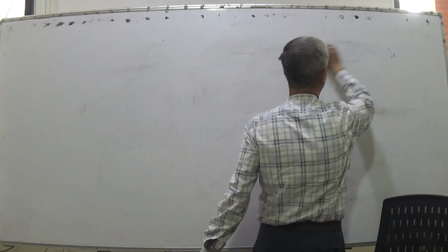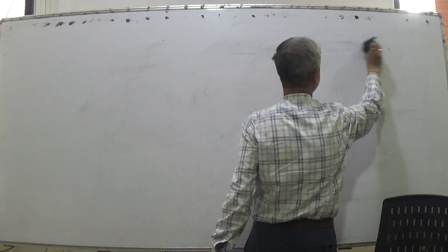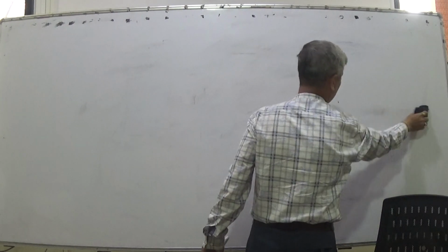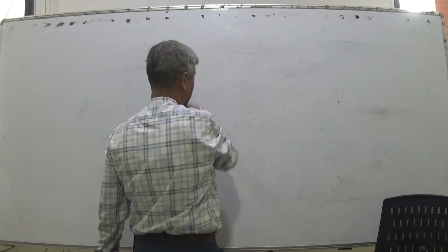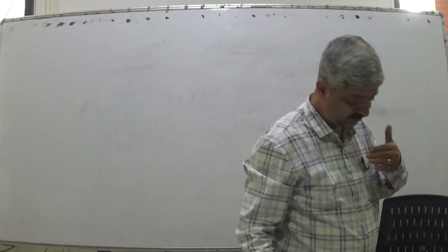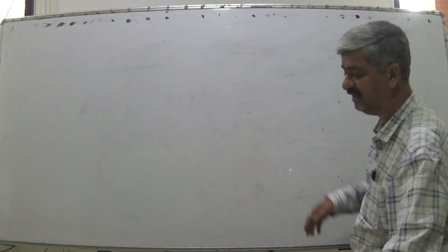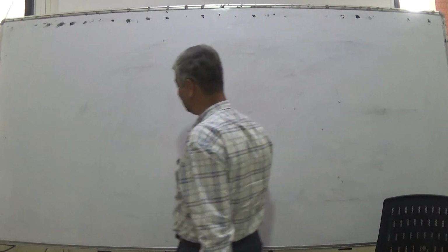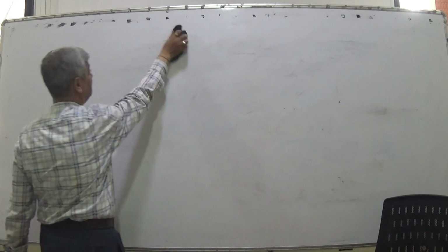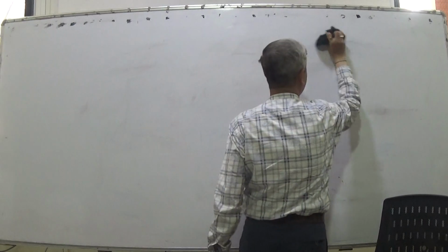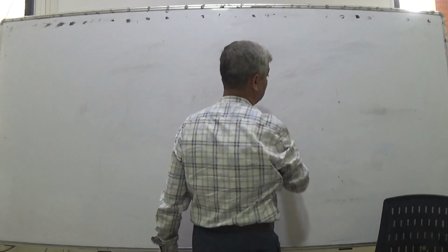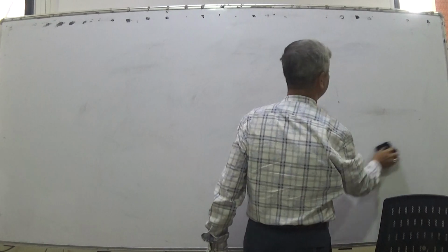The biggest advantage of the analog to digital converter is that it makes it possible for Arduino to read a digital equivalent. The microcontroller needs a digital value, but the values in the real world are continuous or analog. So the analog to digital converter interface enables the microcontroller to read the digital equivalent of an analog voltage.